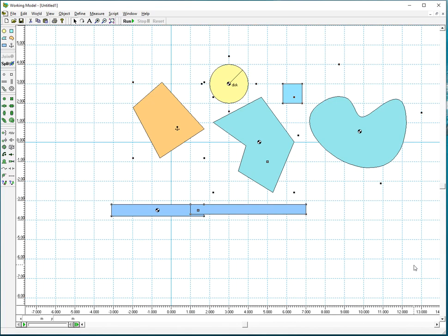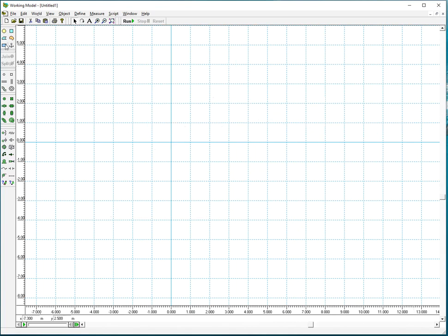Okay, so I'm now going to show how to create a four-bar. I start by creating the links, and of course click and drag is one thing, but for serious simulation you need to watch their geometry. So link length, the first link, I'm looking here, the W dimension will be 2, and I have the first link.